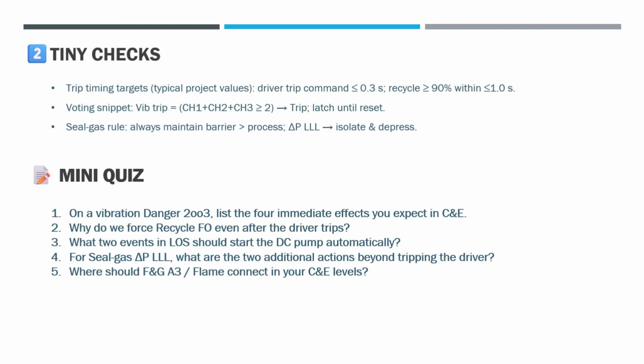Some tiny checks to remember. Driver trip command within 0.3 seconds. Recycle valve reaches 90% within 1 second. Vibration trip logic uses 2oo3 voting. Seal gas rule: barrier pressure always higher than process, otherwise isolate and depress.